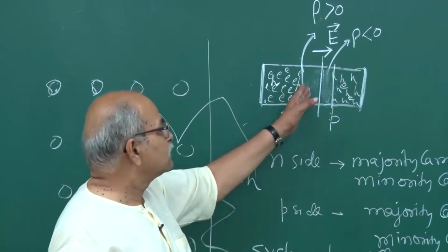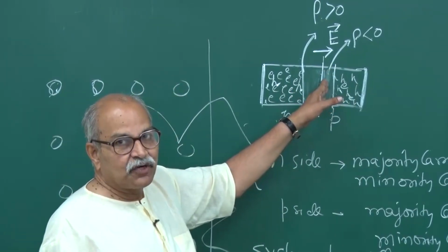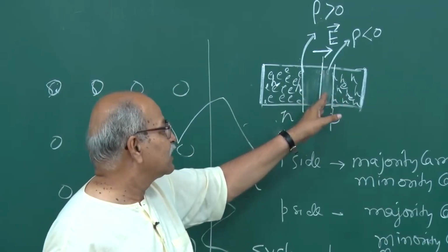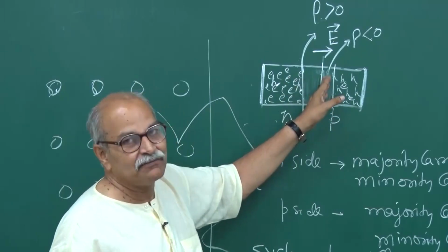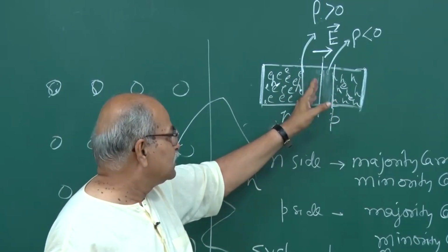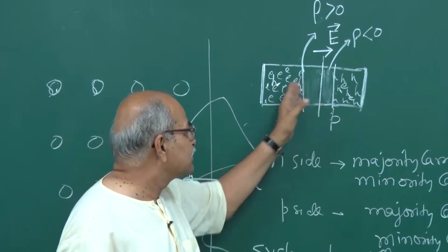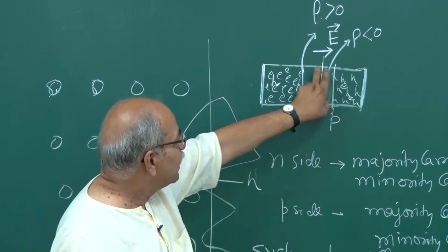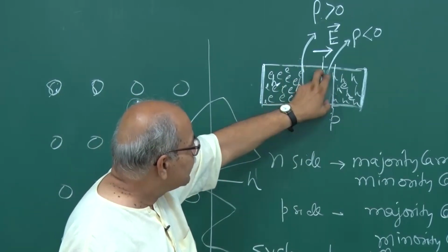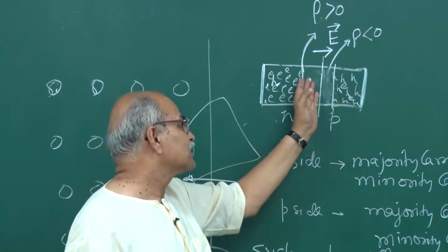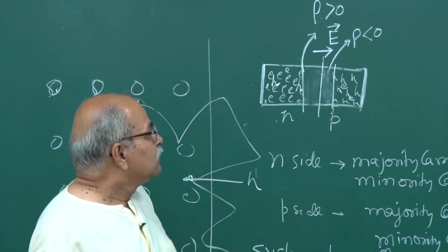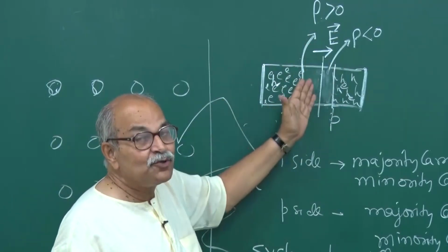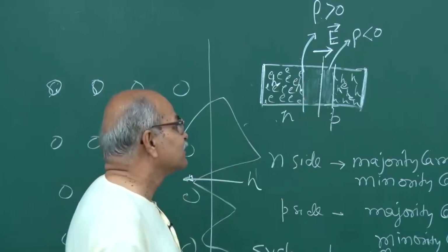The electrons which are diffusing to the right, because of the large hole density there, are trapped, and if there are holes left, more electrons will come, and this width will be adjustable. As many holes are here, that many electrons will go from this side and fill them, and both ways. So, what you find is, yes, there are charge densities, but you do not have charge carrier density.